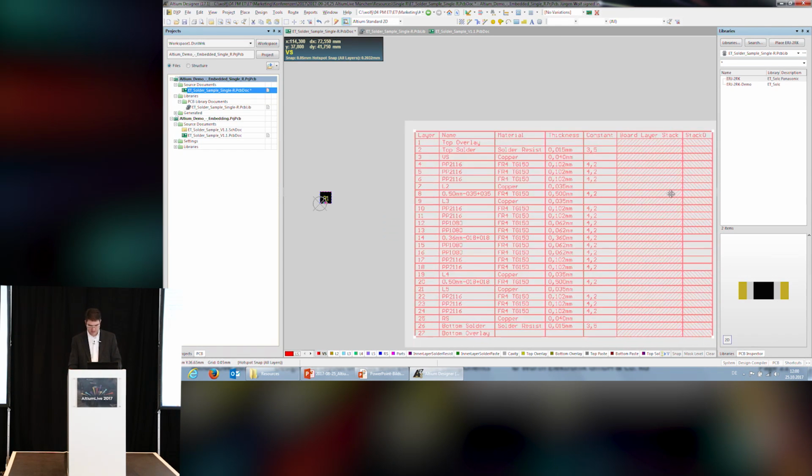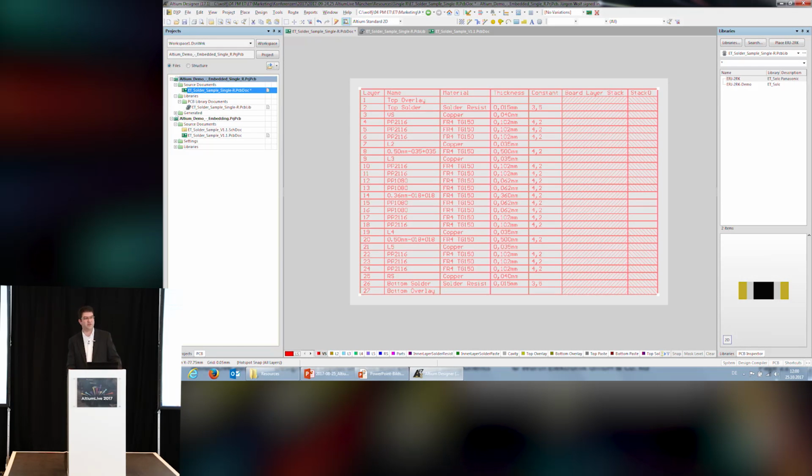And you directly see there is this new stack where we see, as a board manufacturer, which cavities we need. So that's pretty interesting to have, especially as a three-dimensional check. It's unfortunately not yet automated, so that would be one feature I would really like Altium to have in future: a three-dimensional stack with collision prevention for the components on the inner layers. But it's a first possibility to check if everything is okay regarding z-axis dimensions.